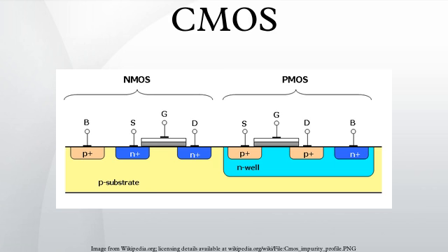Logic. More complex logic functions such as those involving AND and OR gates require manipulating the paths between gates to represent the logic. When a path consists of two transistors in series, both transistors must have low resistance to the corresponding supply voltage, modeling an AND. When a path consists of two transistors in parallel, either one or both of the transistors must have low resistance to connect the supply voltage to the output, modeling an OR. Shown on the right is a circuit diagram of a NAND gate in CMOS logic.